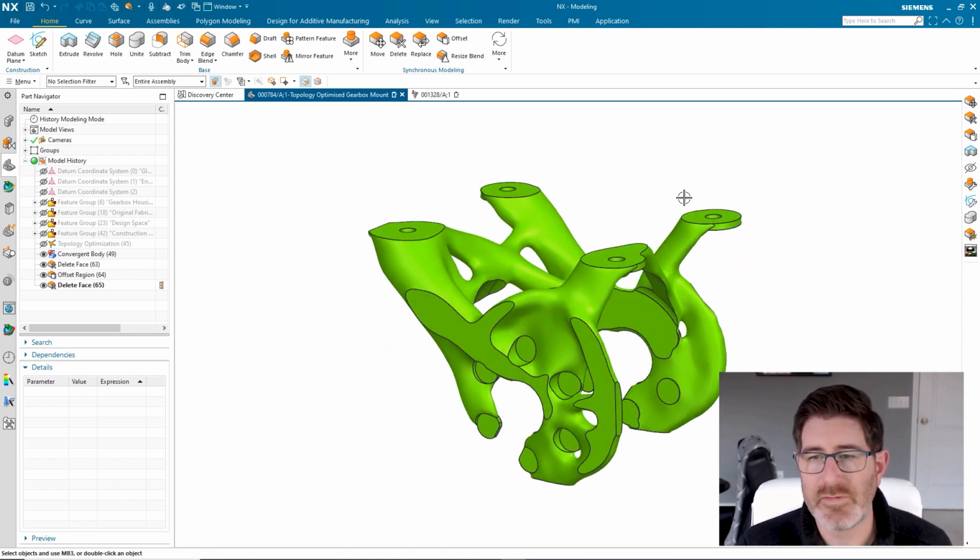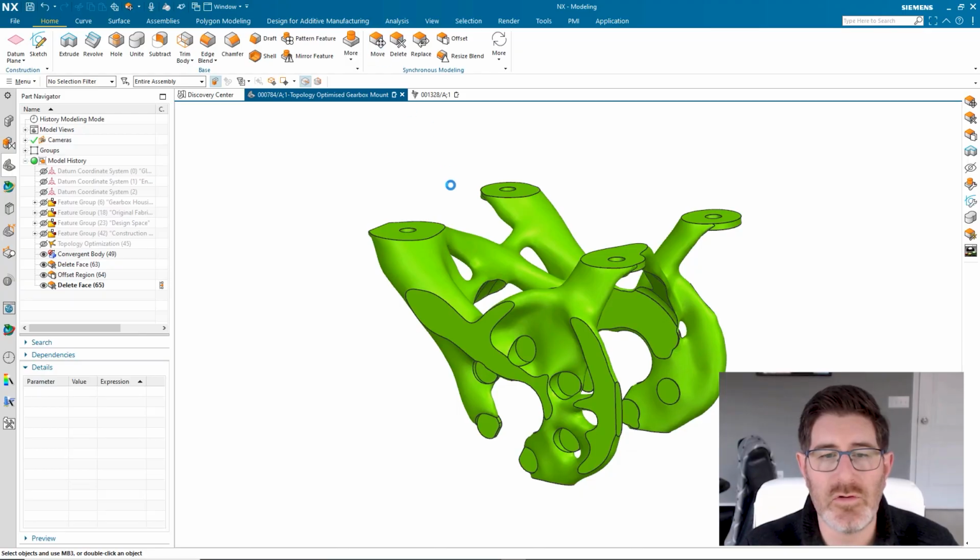The final step is down here on the bottom. We have these 4 sort of feet, and we want those to be all perfectly planar so that when we mount this in the car, it's not going to wobble, it's not going to torque and have any undue stress put on it. So again, we're going to build up those surfaces just a little bit and machine them back so that they're perfectly planar. I'll use the move command to do that.